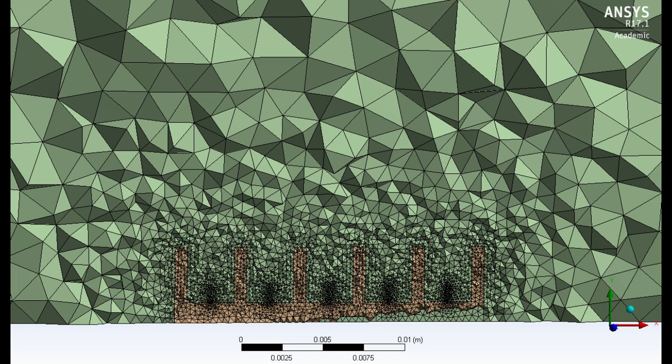The major simplification was to the geometry of the model. The fins and turbulence promoting posts were entirely rectangular geometry in order to obtain a mesh capable of accuracy that remains within the element count limit of the ANSYS educational license.